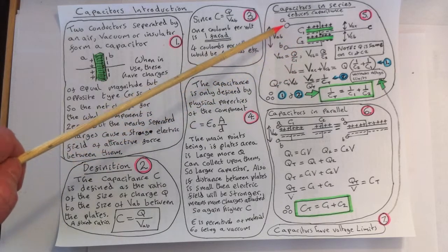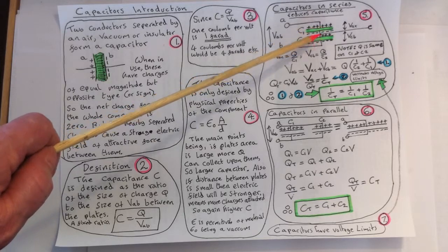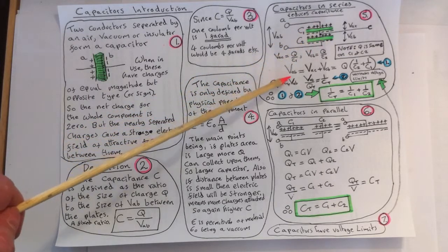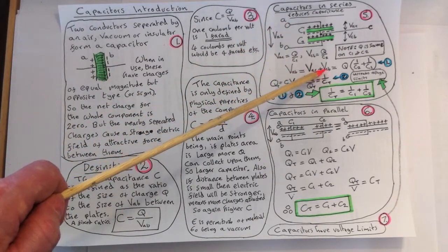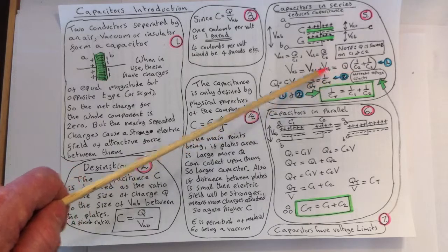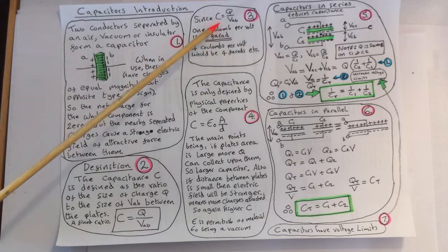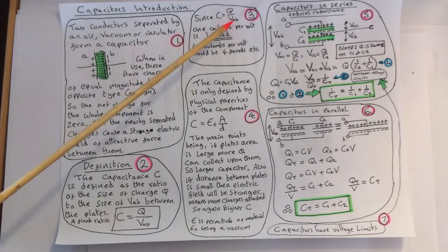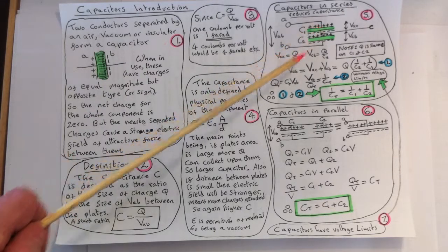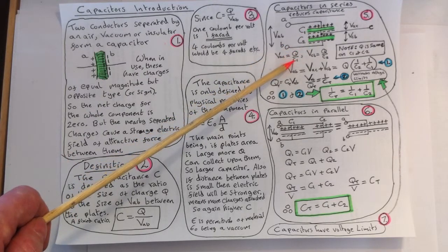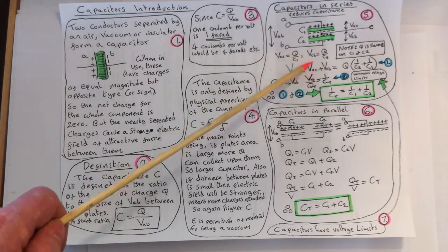So what we're saying is the total voltage is the voltage across capacitor 1 plus the voltage across C2. That gives us the total voltage across these 2 points here. So that's VAC add VAB. Now, as we've said, C equals charge over the voltage between the plates. We can rearrange that to get the voltage across this one is simply the charge over C1. So then using this, we can place these two in here to get this.